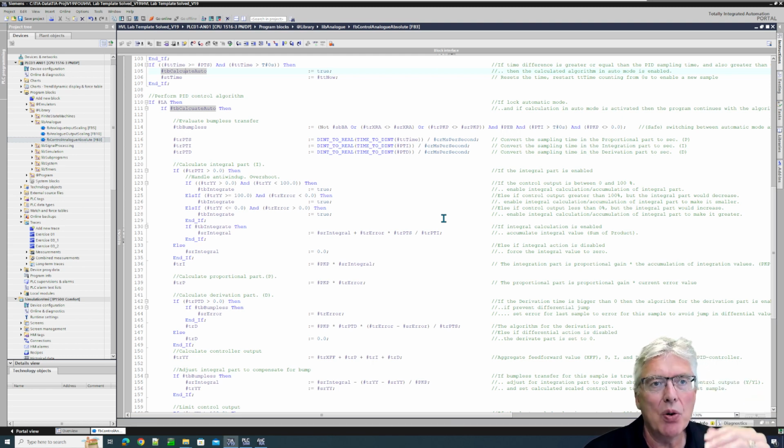I don't get any more, and when I have to switch around and integrate down, my integral value here is in 2000% or something like that, and it's going to take some time for it to get down to whatever value it should be before the output is affected. And this is true also for 0, integral wind up.